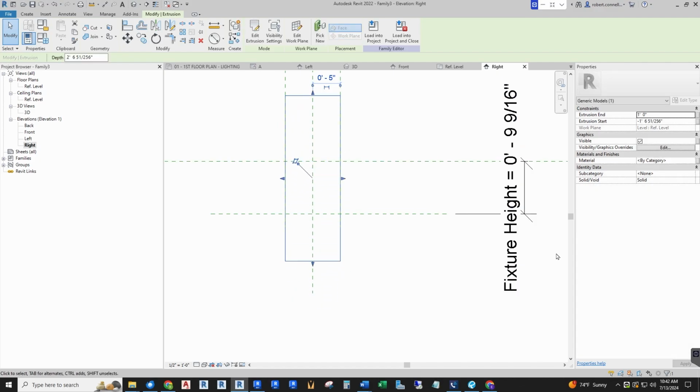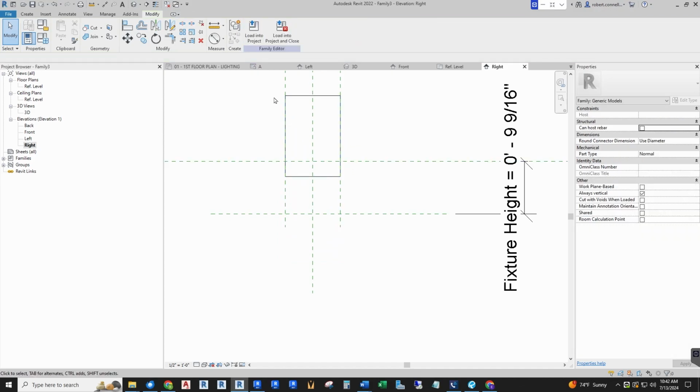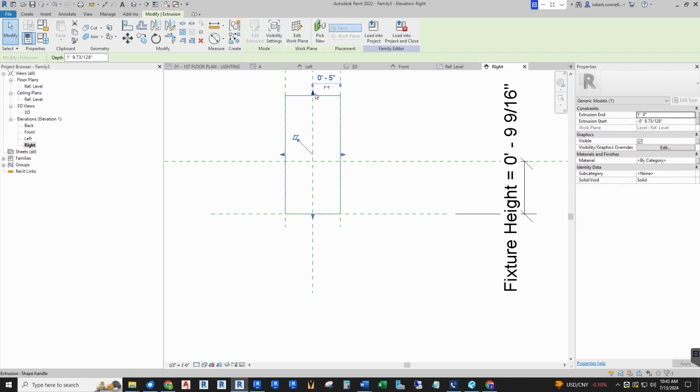It's not locked to anything yet. We can either move it to here, or alternatively, you can go up to the align command up here, align it to and from, and then lock it. Or you can simply drag it, get rid of align, drag it down with the grip.